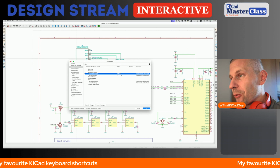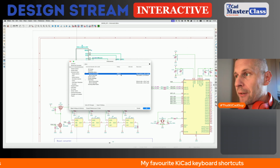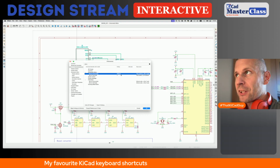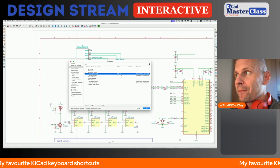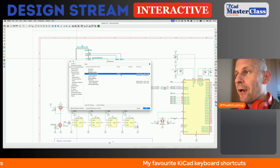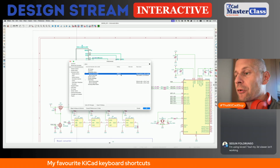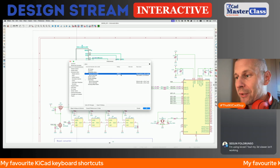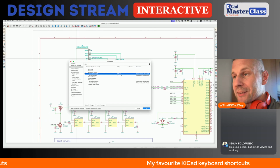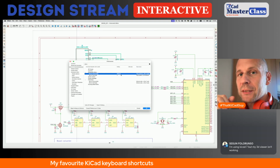Why? Because when I'm working on the PCB layout or component placement, and I have both windows open, the schematic editor and the PCB editor, sometimes the context is switched to the schematic editor and I press X. Pressing X in the PCB editor starts routing, but in the schematic editor, it causes mirroring. And sometimes it happened multiple times, more than twice.